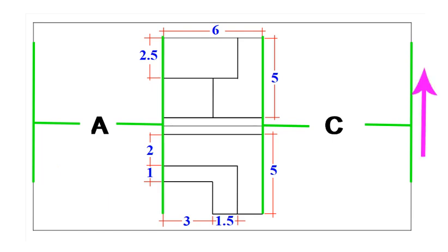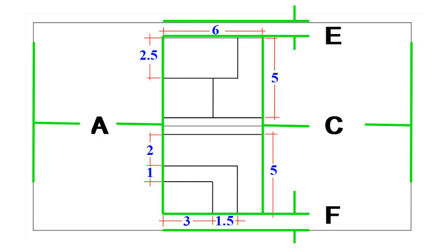Next, the vertical spacing. The distance from the top border down to the front view should be equal to the distance from the bottom border up to the top view. So, E equals F. This centers everything top to bottom.